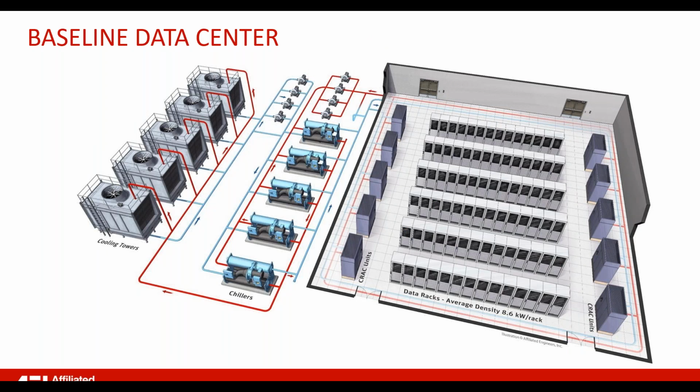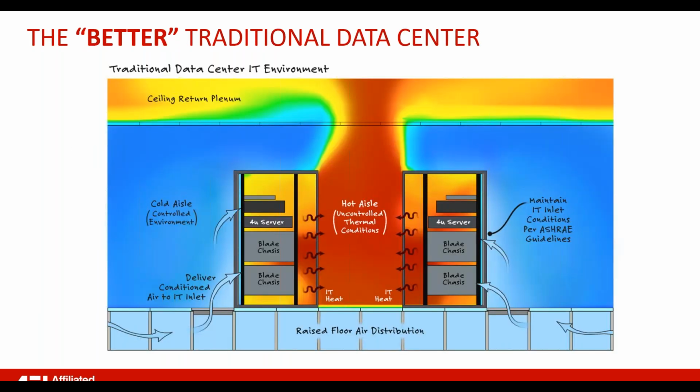Can you go back to the previous slide, please? Yeah, the one thing that we always have to evaluate is how much heat is being generated right directly at the rack and at the server level itself. And some of the phenomena of having recirculation of air and airflow management issues really kind of impacts how the data center is cooled. And that's where the advantageous principle of having some form of containment comes into play. Next slide.